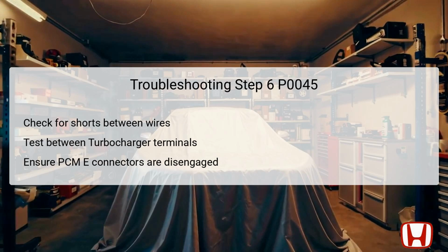This test is crucial because if continuity is present, it indicates a short in the wiring that needs repair. Conversely, if there is no continuity, this suggests that the wires are functioning properly, allowing you to proceed to the next step of the diagnostic procedure.